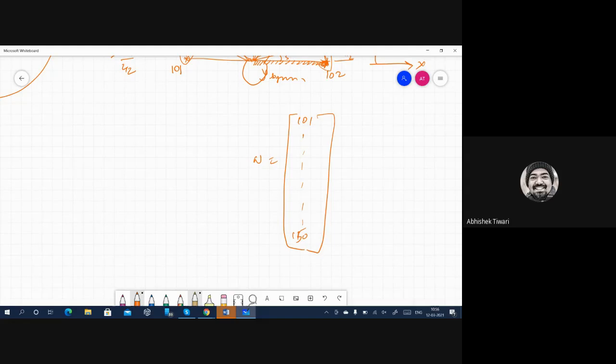So these cars are jammed in traffic. And then you reverse the direction. So on the back side, there is no jam. So some of the dislocations will go freely. So you should have yield strength smaller in the reverse direction, which is called the Bauschinger effect. So we will see in the results if you find something or not. It depends on the material if you have this kind of effect or not. So we'll see that.